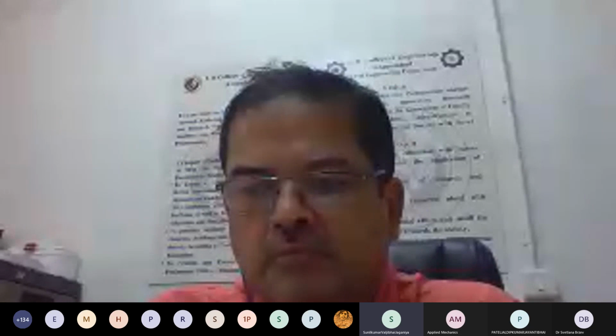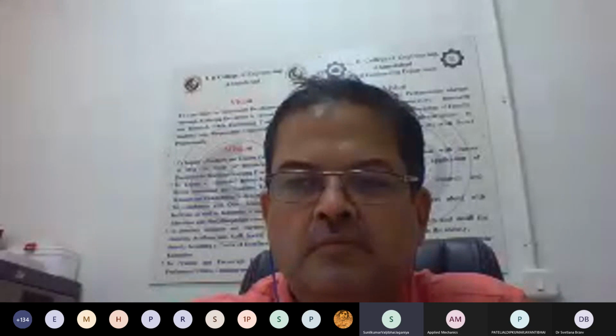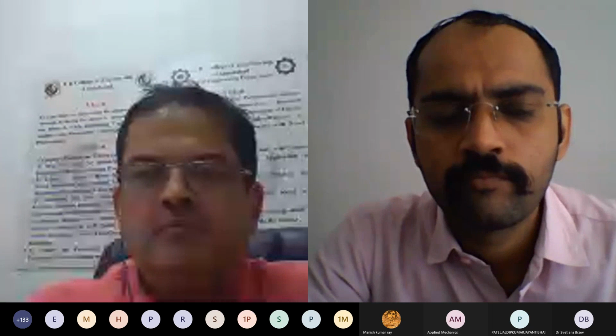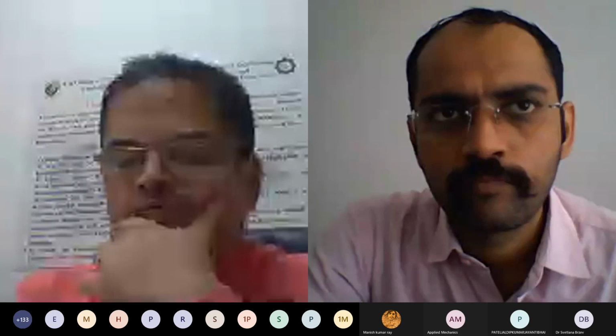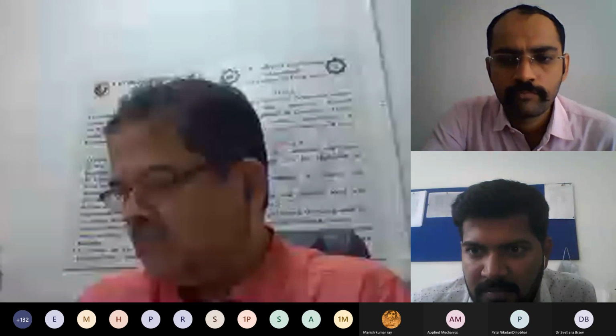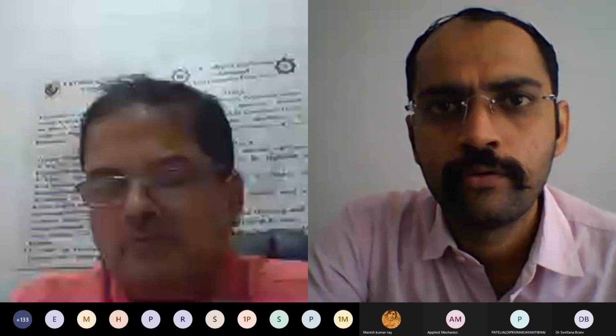Thank you for the question. That is a very important question, because short column effect is really deadly. It's very dangerous, but it definitely happens in columns which are part of a reinforced concrete structure. In confined masonry, you don't have that effect just because you don't have columns. Let's say I'm color blind and I don't see the difference in colors. You should see that it is all the same color, masonry and concrete, because this is just reinforcement for masonry, which happens to be embedded in concrete. So there is no chance of any of these effects that are characteristic for reinforced concrete frame structures.